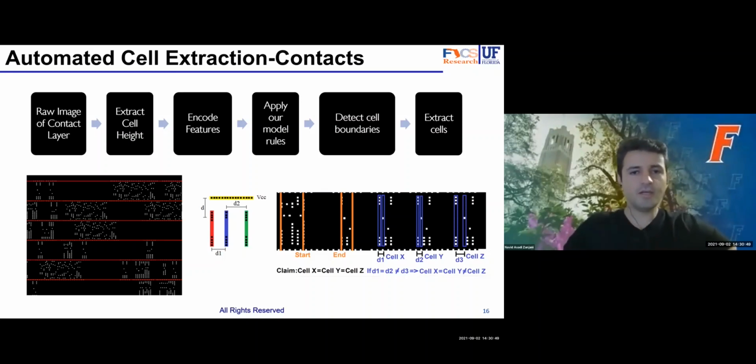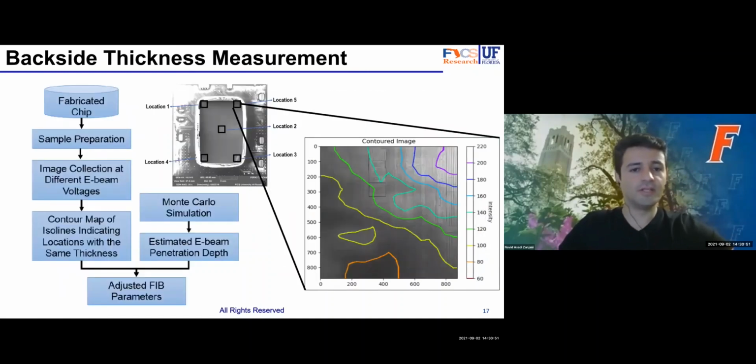Another application, as I told you, when we are doing these delayering processes, a lot of times stuff like this happens. You have the silicon where it's removed, but it's not very uniformly removed. Some areas have a little bit, so here which is darker, there is more silicon left, and we are talking about nanometer scale, right? Maybe here there is 5 nanometer silicon, there is 15 nanometer silicon left. But if this is passed through an algorithm to identify the contacts, they are going to be challenged.